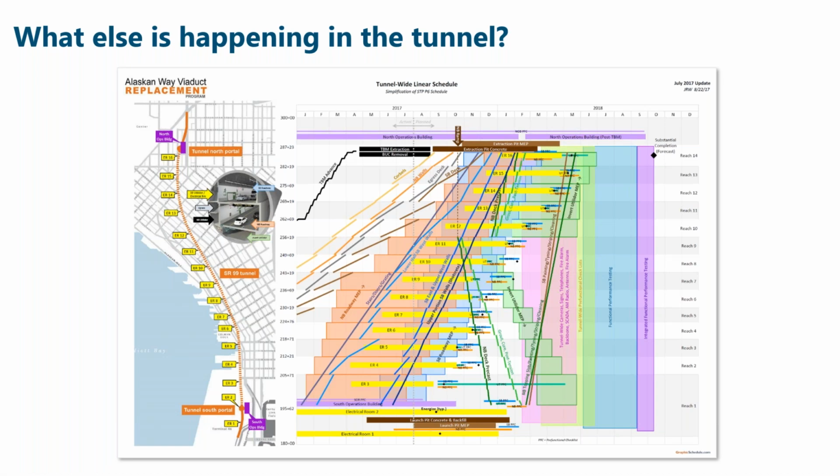Why is it so, James? Because at this time, in October of 2017, there was still a lot of activity here, and they wanted to get started on the deck, so they started early by starting it right there and working south. So they started behind and worked backwards, and you have to work backwards with the precast decks, because once you set it, you cannot drive past the precast deck.